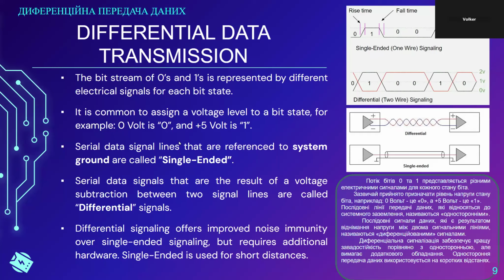The differential driver is subtracting the signals. And the big benefit is that noise signals or ESD, anything that happens to the data signal that would destroy a single-ended signal, is simply subtracted. It is eliminated in the differential driver.